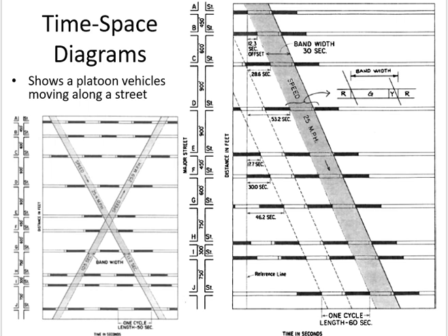If I put 77 seconds, I skip the whole cycle, since 60 seconds of that is a full cycle. So how can you skip the entire cycle and give me the second green? You cannot do this. You have to give me the first green. The first green will end, then the red will come, and then the next green will come. So we are putting the time for the first green for all of these. Whenever the offset goes more than one cycle, we have to subtract the cycle length, so I have the time in the first cycle.